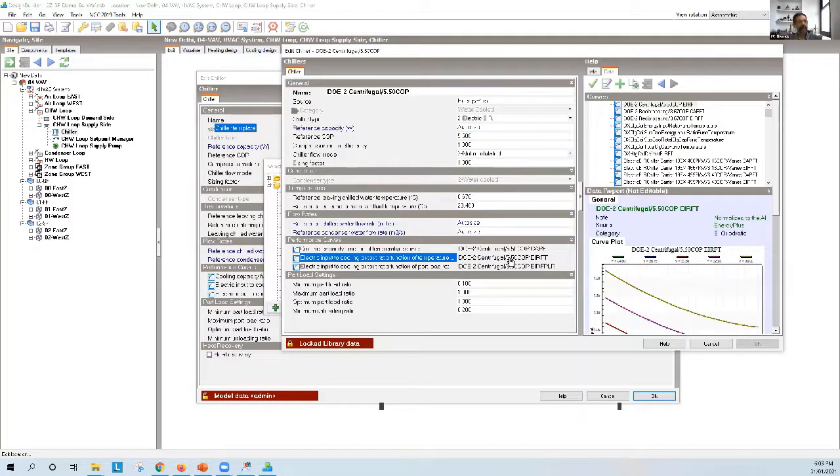And you've got a whole bunch of different curves for the fans. There's an Appendix G curve for all the variable volume fans. You should use those. They're probably the best thing that's available right now. Just remember, when you're modeling pumps and fans, you're not just modeling the fan or the pump. You're modeling the fan plus duct system. And no one's designed the duct system at the early stage. You only get that when the contractor comes in and works out the lengths of the ducts and finds the resistances. So you don't know what the resistance is. So we've got an average set of curves that ASHRAE has put out, which are these Appendix G curves.